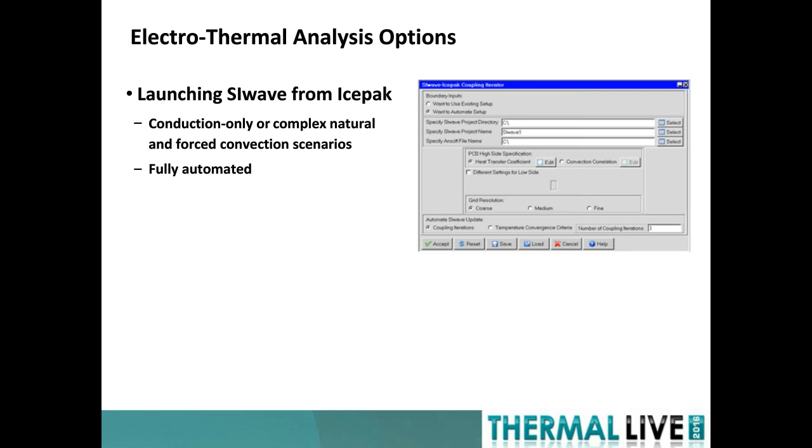However, if you are handy with convection coefficient tables and heat transfer textbooks, you can just refer to those. I'm sure there's some good tables on electronicscooling.com, the Electronics Cooling website, and also in just heat transfer textbooks. I think there's a lot of information on convection correlations, and so if you're familiar with that information, you can just refer to those tables.